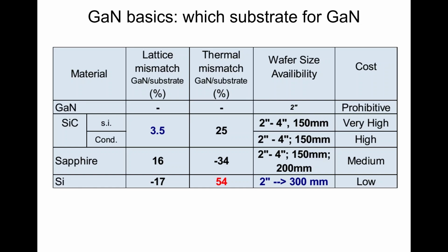Silicon carbide is always there as a substrate in this case. Beautiful substrate. This is the mainstream in RF devices. Definitely, GaN on silicon is just for some of the applications, but if you want high power in the gigahertz-plus range, you want to use GaN on silicon carbide. Sapphire is not really an option. I'm not aware of it outside optoelectronics. I'm not aware of it for power, as the thermal dissipation is so poor that it's very difficult to use. Though some companies claim the opposite, my opinion is that the thermal penalty will be too high.